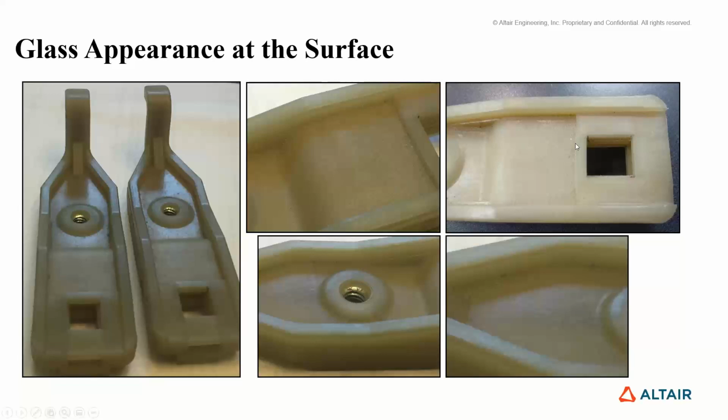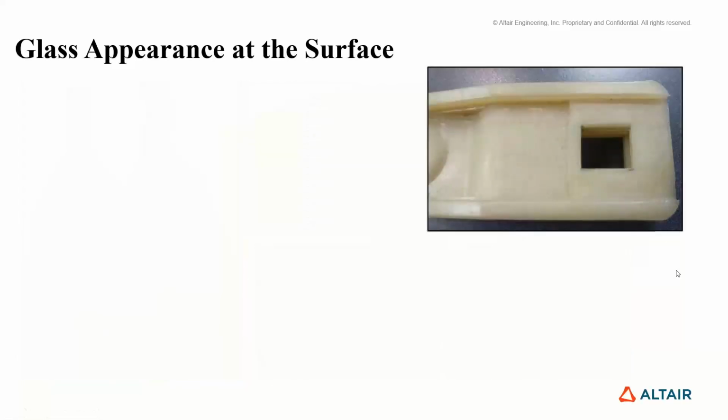So there were mechanical issues in addition to the molding issues, and so you'd see a little bit of glass at this end, and once you got a flow front that made it around this feature here, there's a slide that comes in and cores that come from the top and bottom. Once it got around this, then you could flow really fast, and so it would speed up. As it sped up, especially coming into this corner, the flow front speeds up a bunch. And so then you see that resin-rich surface emerge as it gets toward the end. Another example of that, with different lighting to really highlight that glass at the surface in that part.